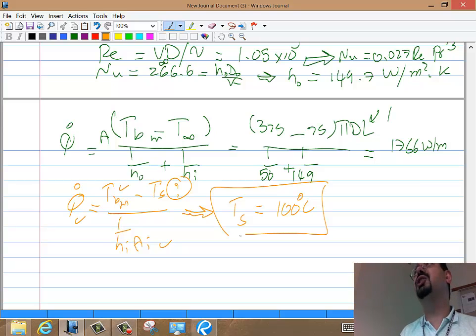You will get the same correlation. You'll end up landing on the same correlation. And then the Prandtl number is almost the same, and the k is almost the same. I will end up with the same h. Why should I go again? So it's not really how far the temperature is, it's how far the properties are.